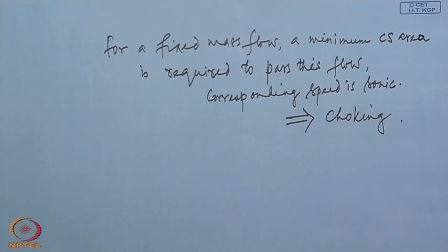That is, if we have a fixed duct with say minimum area at its exit, we know that the maximum mass flow that can pass through that area can pass only when the exit speed is sonic, and this will need a fixed inlet flow velocity, of course subsonic, and for any other conditions the flow in the duct will not remain steady.